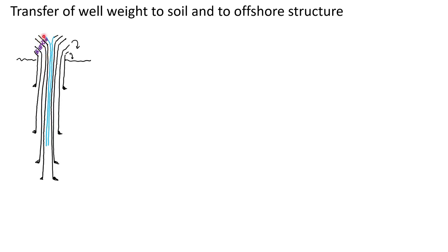That's why you have seals that prohibit the outer tubular strings from being exposed to the inner pressure. In this case you have the annulus, which should tolerate the reservoir pressure, but maybe not these ones. The other ones have to be protected, and I need to have a seal.